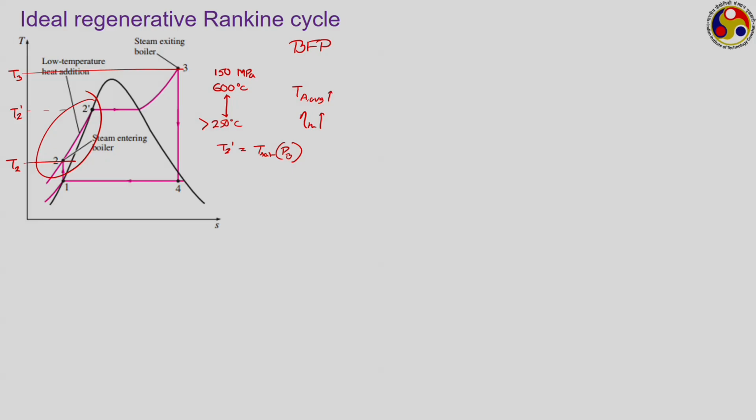You already have studied the Brayton cycle, and there we have seen that the exhaust gases that are going out after the turbine expansion, the heat remaining in that exhaust gas is generally used to raise the temperature of the air before it enters the combustor. But that kind of option we do not have in case of a Rankine cycle, because here nothing is going out in a way. It is a perfectly closed cycle, and the water or steam, whatever we may call the working substance, is bound within the domain of these boundaries.